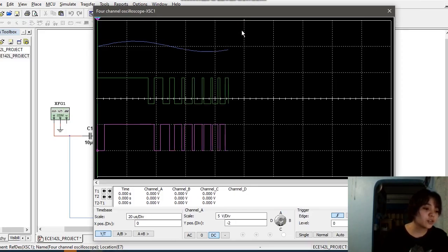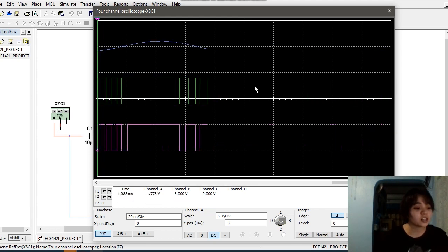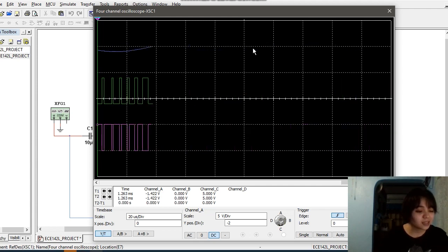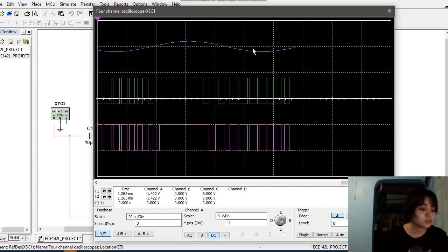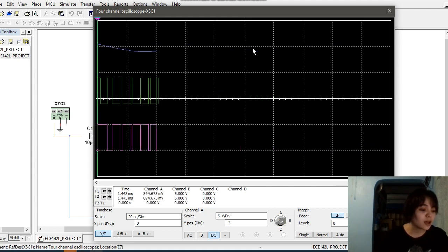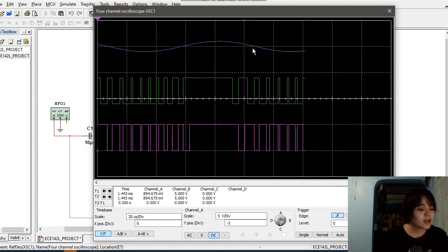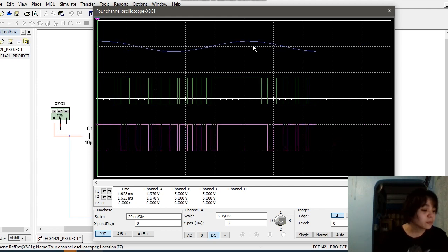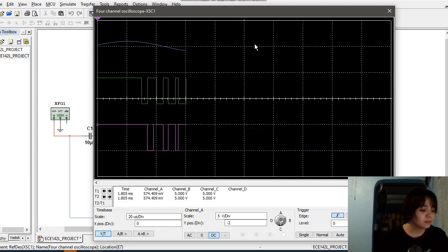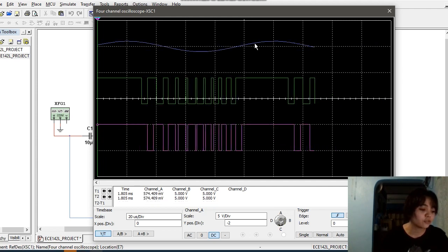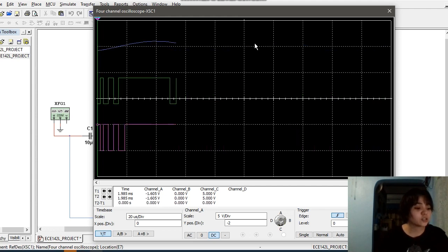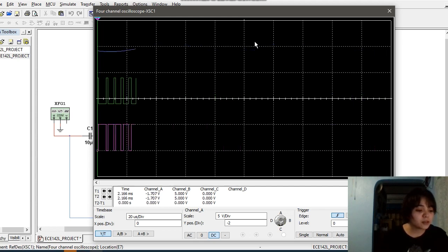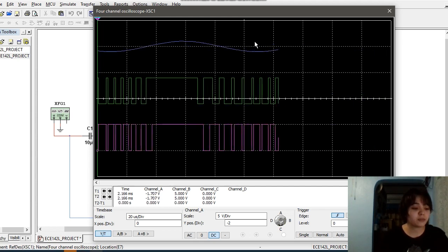For the description of each waveform, a key difference between PWM and PPM is that in PWM, the width of the pulses shows proportionality with the amplitude of the message signal, whereas in PPM, the position of the pulses is proportional to the amplitude of the analog modulating signal. It is to be noted here that the position of the pulses changes according to the reference pulses. Basically, the falling edge of PWM pulses acts as the starting of PPM pulses.